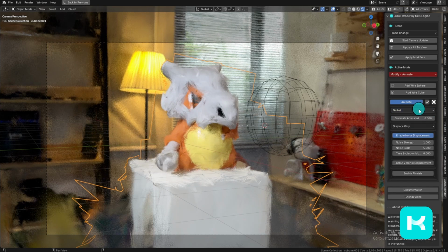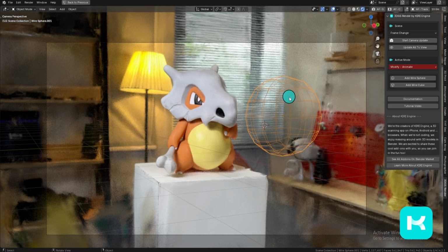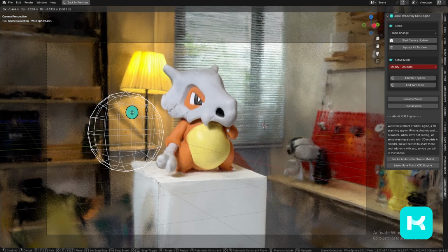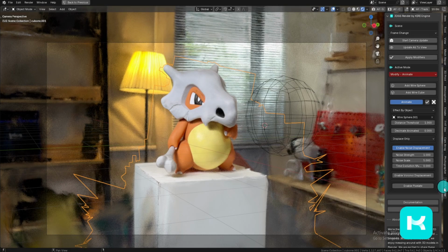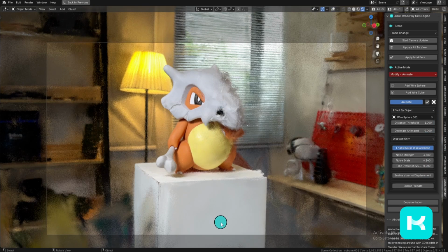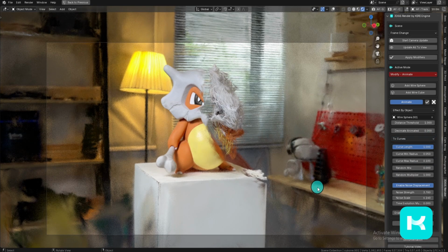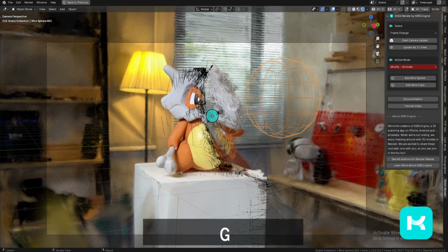Animation effects can be global, applied to the whole object, or by distance to a selected object or collection that we'll also refer to as effectors. If effect by object or effect by collection is chosen, a distance threshold will appear, and anything below this will be animated. There are 3 modes of animation: displace only, to points, and to curves. Each mode supports some of the following effects.